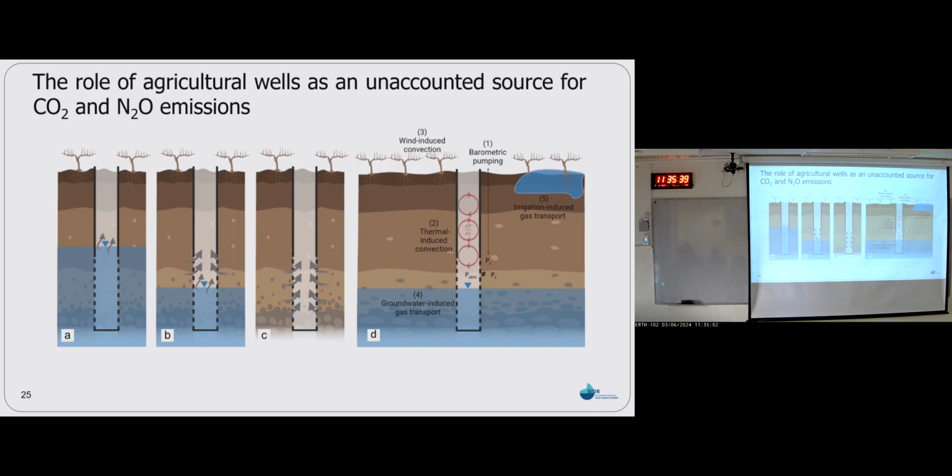But suddenly, you have to think of it like a straw going into the deep soil. This can be 10 meters, this can be 100 meters. And these are the perforated sections, areas in the soil that didn't see atmospheric values of air, suddenly seeing the atmosphere. So air from the atmosphere can go inside and interact with the air inside the soil at 100 meters, for example. And this starts to be problematic because here you sometimes have elevated CO2 concentrations, methane, different VOCs.